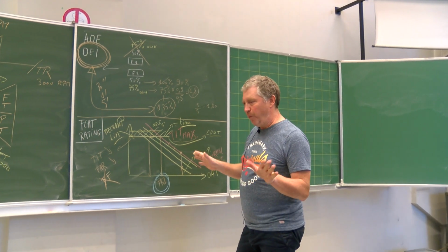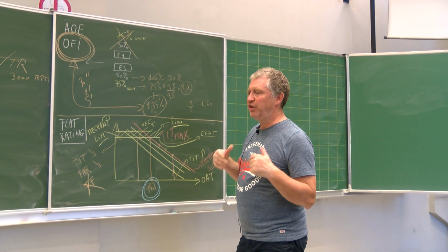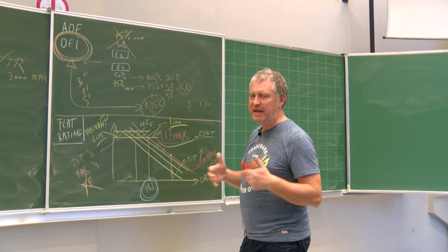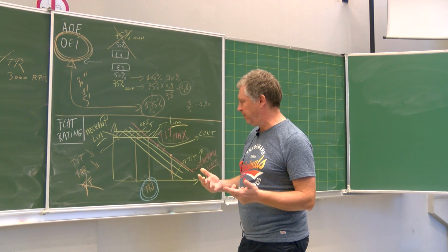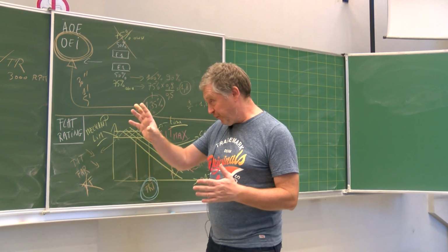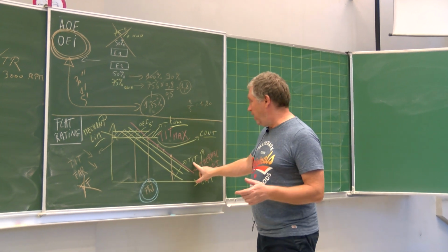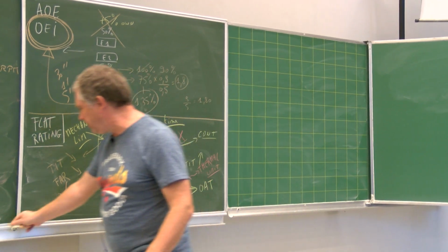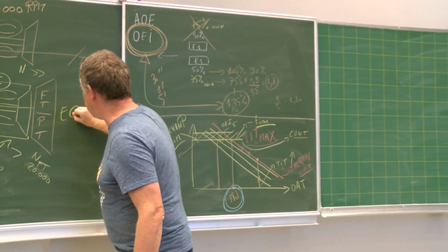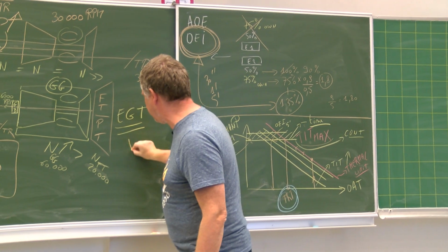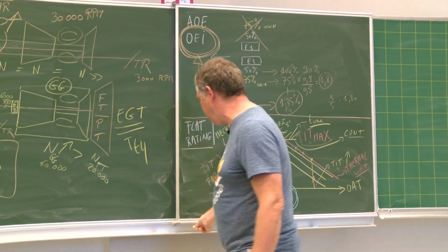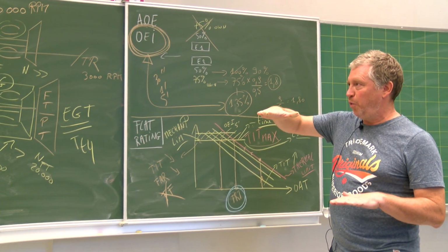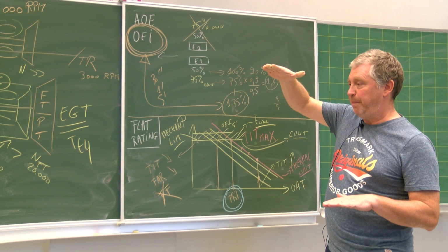You are raising the blades, and the power you need to drive these blades at a constant rotation speed is increasing, increasing, increasing. And so what do you see? In front of you, you have an indication related to the TIT. It will be more the EGT, the exhaust gas temperature. So this is TT4, not TT3. And you will see the EGT rising, so going up.